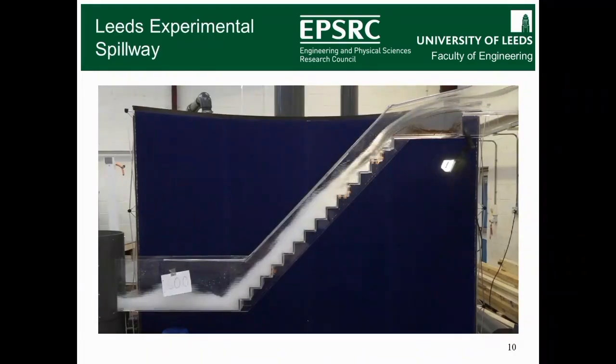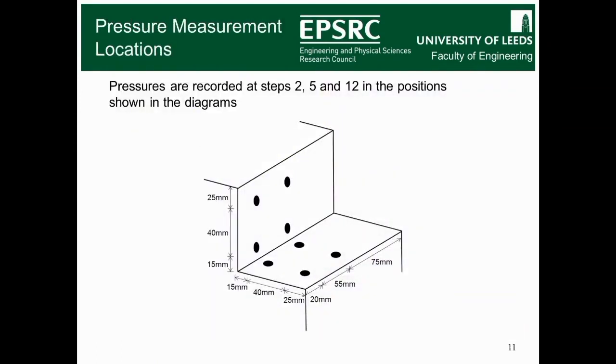So the next spillway that I modelled is one that we designed for the University of Leeds. Again, the video is really slow. It's relatively narrow, 150 millimeters wide, and it consists of 15 80 by 80 millimeter steps. And you can see, even though the video is slow, the non-aerated region, the inception point, and the aerated region. And we've taken pressure measurements at steps 2, 5, and 12. And at these steps, these are the positions we've taken our pressure measurements on both step faces, at the center line, and also at the wall.